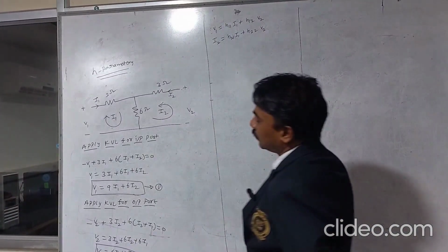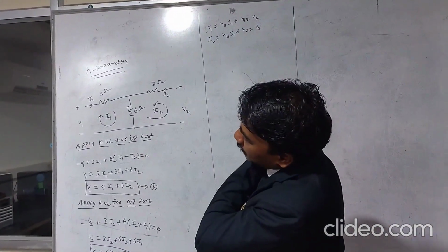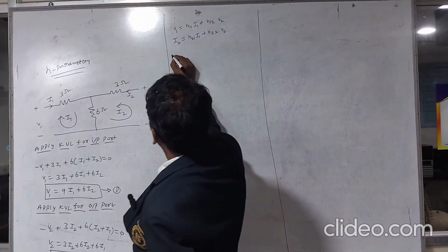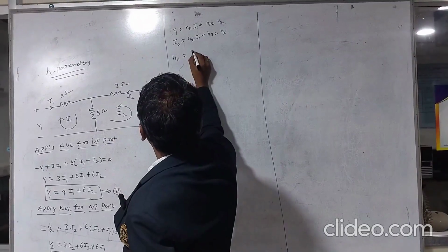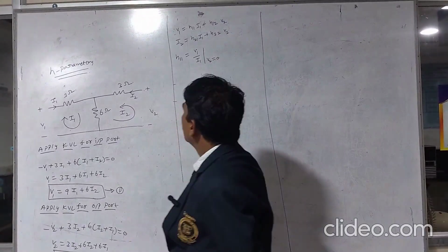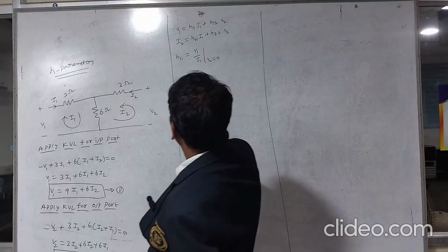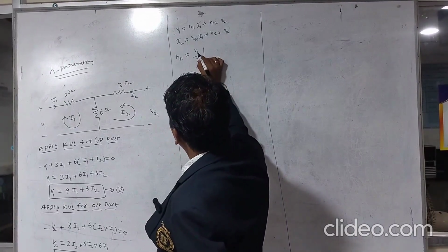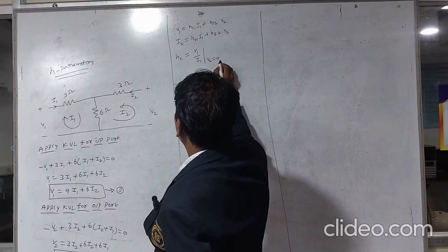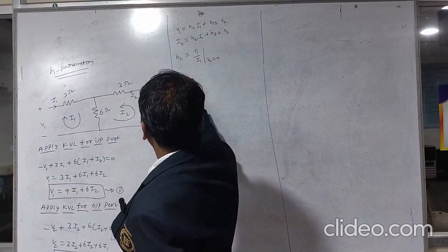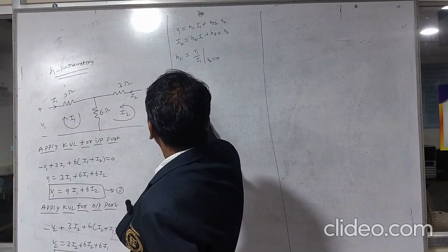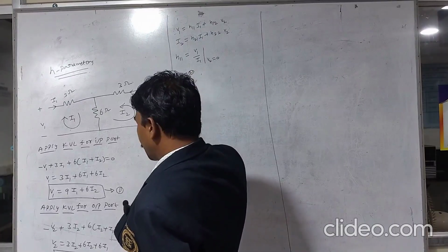Okay. So now the given network belongs to a T network. We are writing the KVL equations. These are the generalized equations we are getting, 1 and 2. Now to determine H11, V1 divided by I1 where V2 equal to 0. So this is nothing but input impedance, since V1 is the input port voltage and I1 is the input port current, by short circuiting the output port. Okay, fine. So what's the condition here? When V2 equal to 0, from equation number 2,